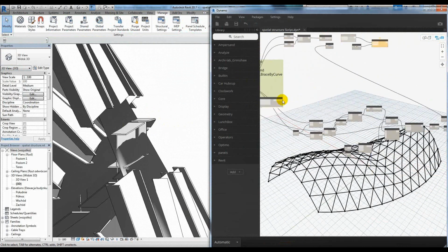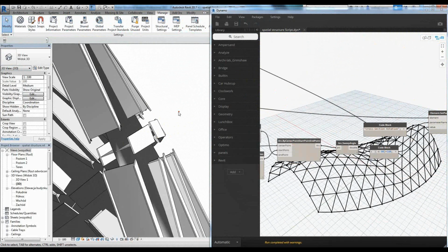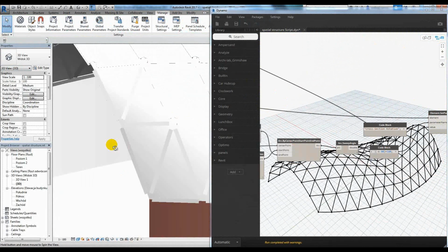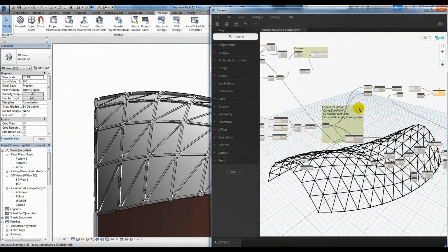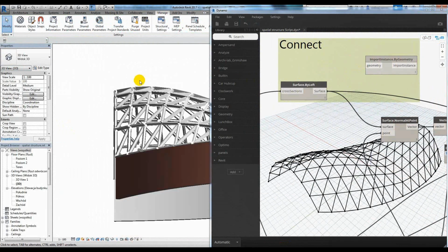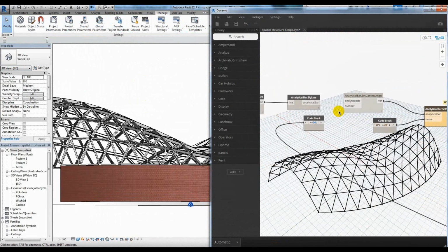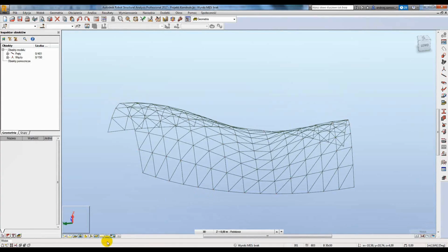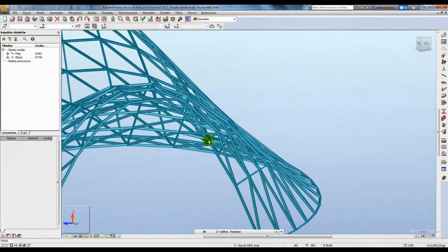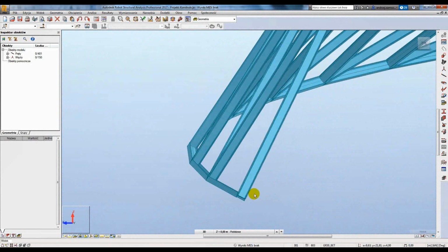This example shows how flexible and how versatile the solution is, because you can really create very, very precise information, and you can stream that information into your model. As you could see here a couple of seconds ago, I was even able to calculate each individual rotation angle for each individual steel beam in Revit in order to place this beam orthogonally to the surface of a roof, right?